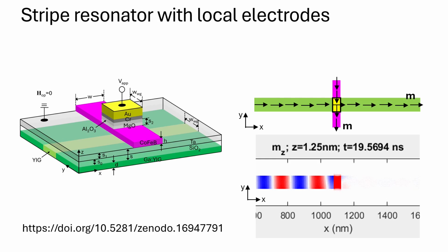We put this design of spin wave well to the test by running micromagnetic simulations. In the simulation, spin waves are injected from the left into the magnonic waveguide towards the right. When the spin waves reach the underneath region of the stripe resonator, the spin waves set the resonator into precession and are being absorbed. Notice that the oscillation in the resonator is confined to the area covered by the top electrode and does not propagate to the area on the stripe not covered by the top electrode.